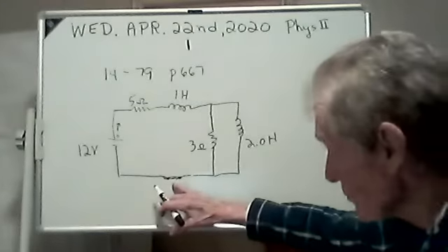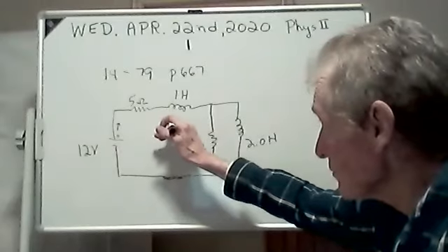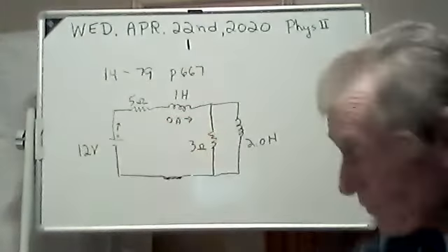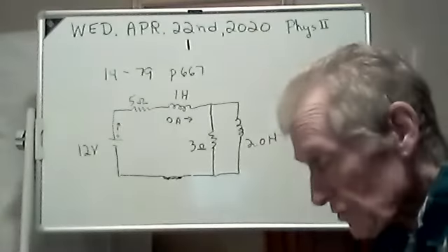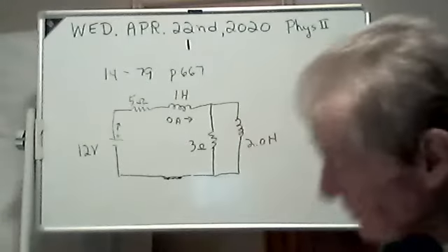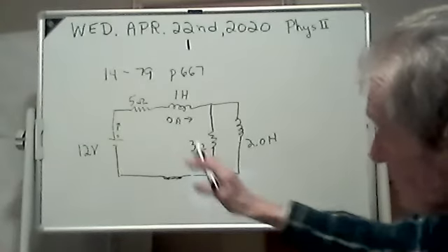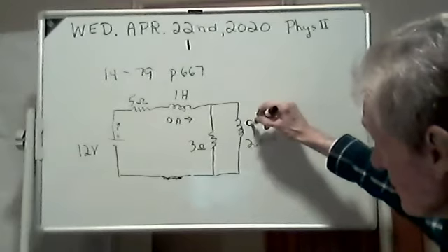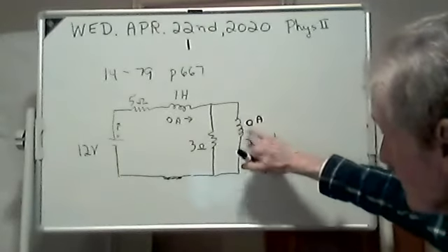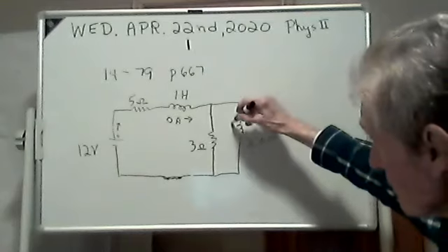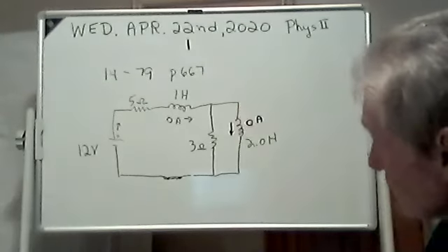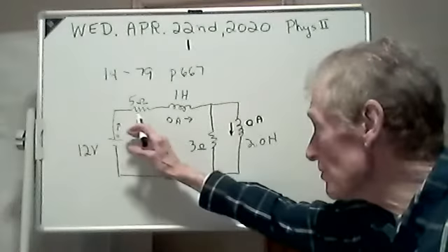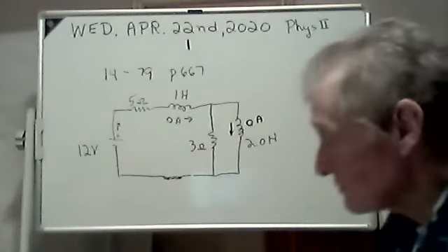And so when you first throw that switch, the current through here is 0. 0 amps is what you had before. And immediately after you throw the switch, 0 amps is what you have now. It's going to build up. And there'll be a current, all right. And the same here, there was 0 amps in this coil here, in this inductor here. And so there'll be 0 amps immediately after you throw the switch. Well, there's no current anyplace. You know what? There's no current here, no current anyplace.